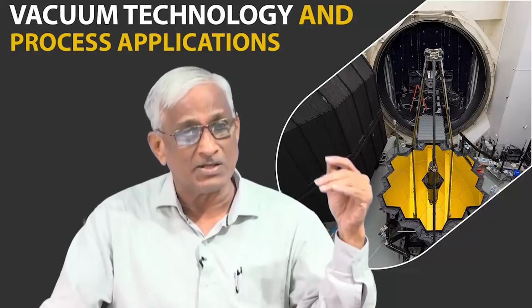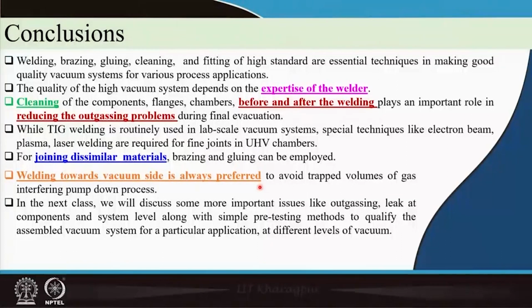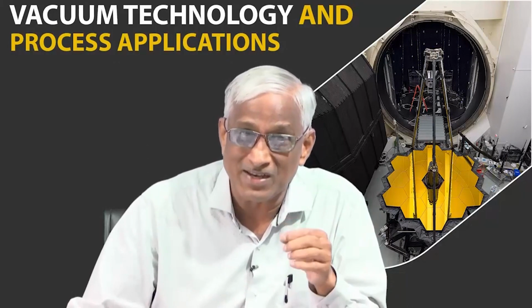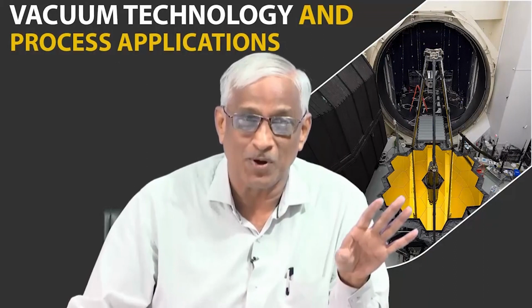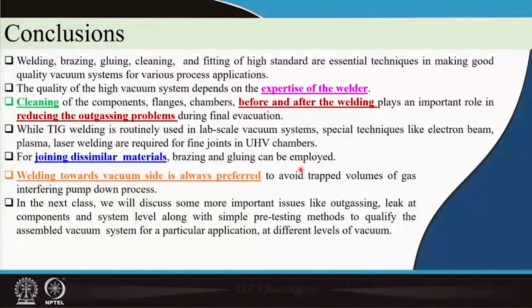For joining dissimilar materials, normally brazing is used, and welding is always preferred on the vacuum side. That is why I am again referring to it, otherwise it will create pockets, which are very dangerous. A small pocket can give you a 10 year problem in not getting vacuum. I am just exaggerating, it may be 1 year.